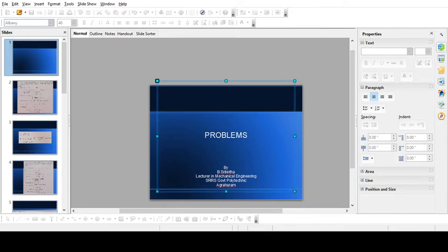Next, the change in the volume. We know that bulk modulus is equal to direct stress by volumetric strain. So volumetric strain EV is equal to direct stress sigma by bulk modulus K. Now, 100 by 0.67 into 10 to the power of 6.